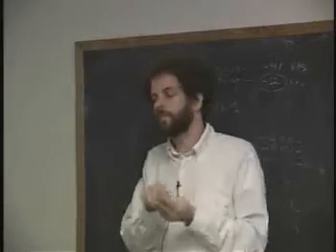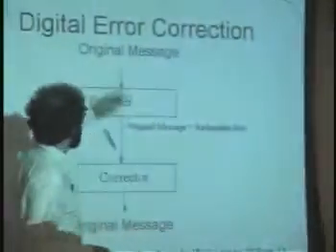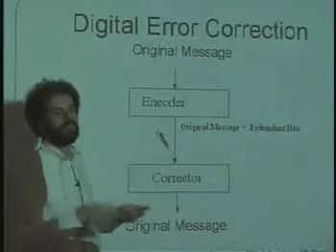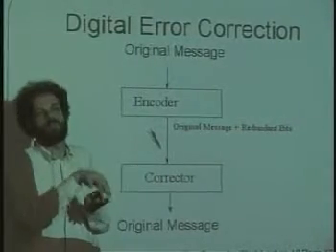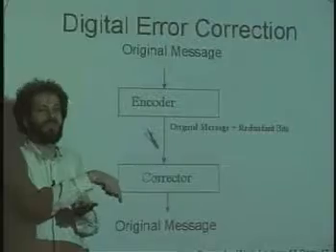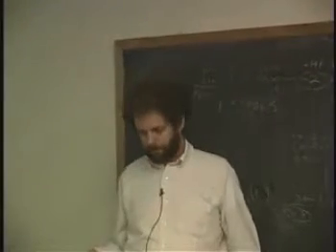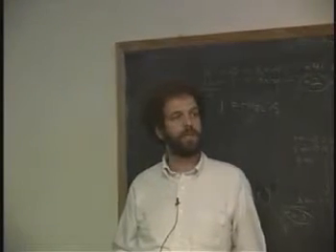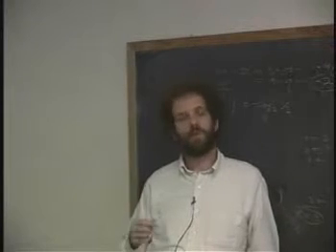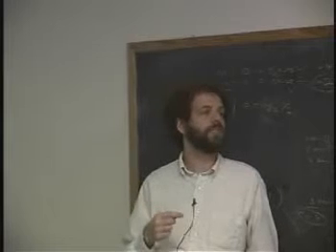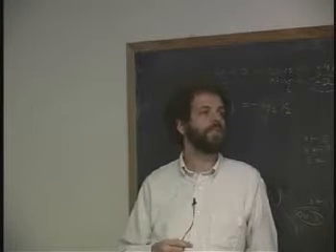And so you can build a system, a very inefficient one, it turns out, that just multiplies the number of bits that come in by 3 and can withstand up to any one of those bits being bashed, as long as you don't bash 2 in a row or 3 in a row, as long as you skip 2 before you hit the next one. And in general, the modems that we use, the cell phones that we use, the laser discs that we use, a CD and things like that have all sorts of redundancy that is put into the bit stream in order to allow correction to be done for bits that are found in error.